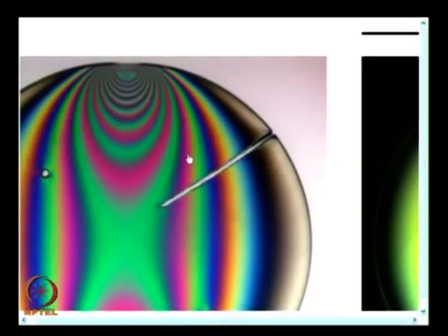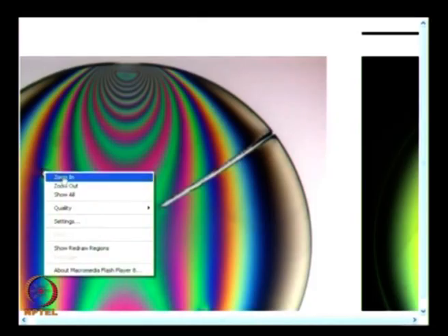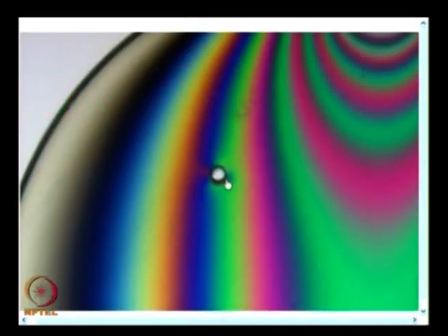And if you take that kind of care, what this fringe pattern shows is, when I have a slit made, the fringes are not disturbed, and you have a slight difference here. Here a hole is made; though the hole is made reasonably well, you find there is some small disturbance. It is not as good as what you had with the slot. So, the person who has made the hole needs to improve his process, because you have some small disturbance. So, even this could be eliminated by careful machining.